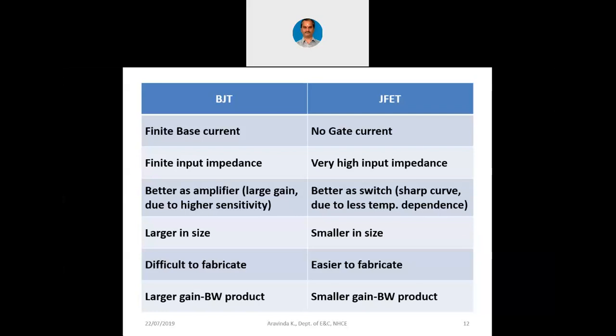I am telling you about these foundries. Now if the device has an easier design, then it is easy to fabricate. The process of fabrication is nothing but the process of manufacturing this device. Silicon wafer has to be taken, then the wafer has to be doped with N-type and P-type, and then after doping, it has to be insulated, gate, drain, source connections have to be taken out, or emitter, base, collector connections have to be taken out, and then it has to be packed to be used.